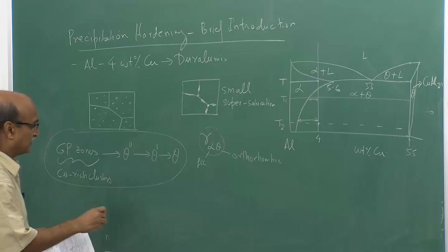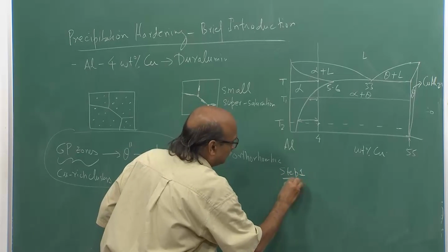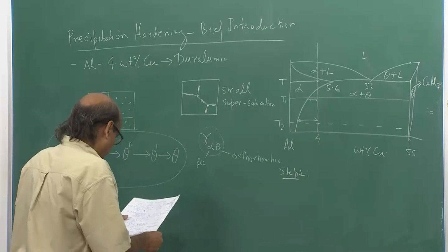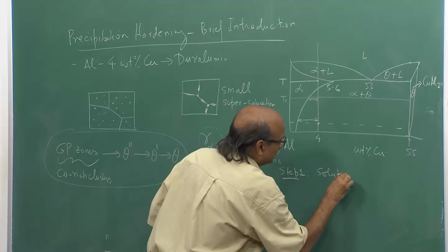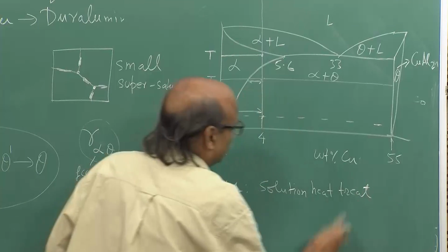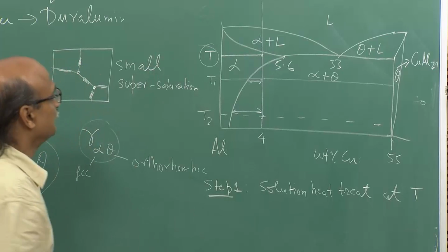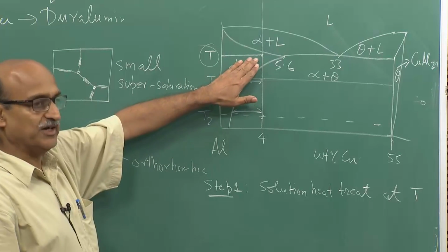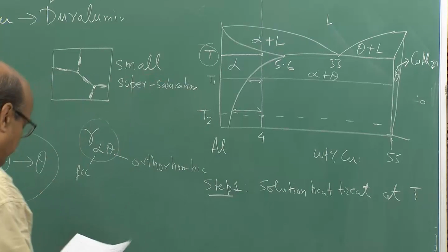What you do is, as step 1, you solution heat treat at a temperature T, so that everything is single phase, everything is solutionized.